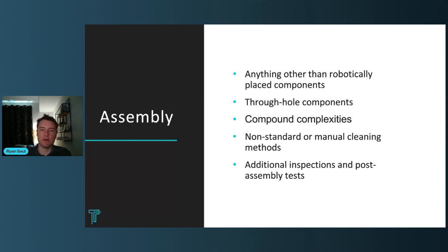Don't get me wrong. They are mechanically more sound. They're thermally more connected to the core of the board. It's a good job to use a through-hole part sometimes. But test points is an example where there's really very limited value in having your test points be through-hole, unless there's going to be a lot of physical grabbing and manipulation of your board by its test points.